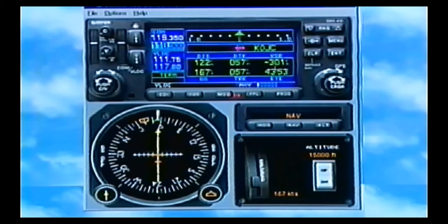So what I'll do is I'll just fly along. When I see that thing get close to 500 feet per minute, I'll just start down. If I pick up a little speed on the way down, it'll go to a little bigger number, tell me to go 500 or 600 feet per minute. If I throttle back or slow down a little bit, it'll go to a smaller number. But it's a fantastic function. I do recommend trying it out. Once you set it up and look at it, you'll understand what it's doing.